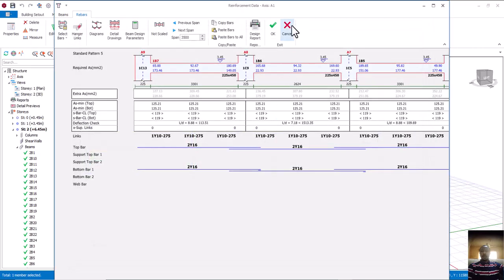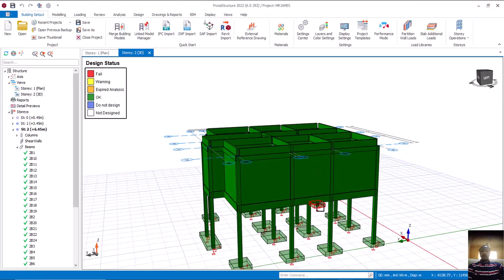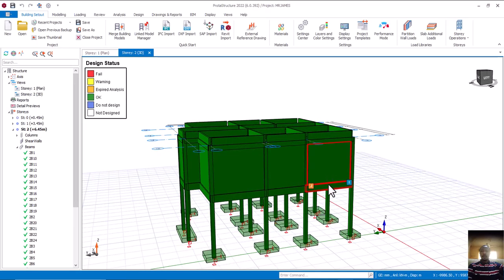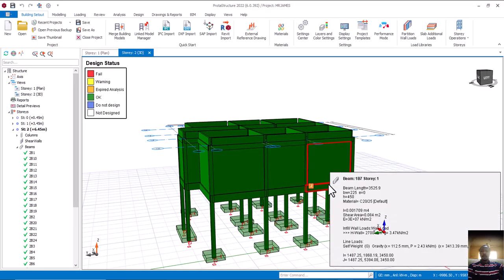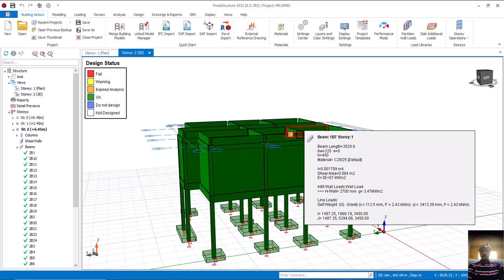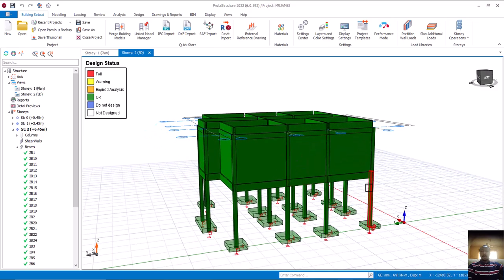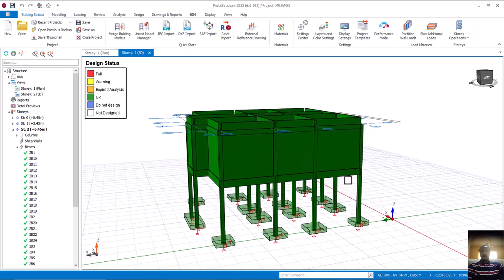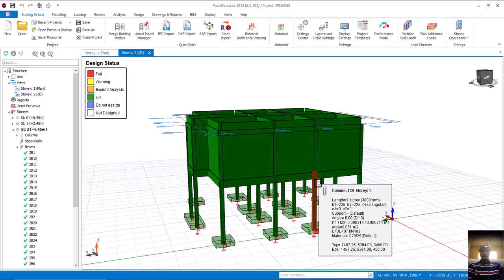So now that you have done these settings, the next thing, how do you take it to AutoCAD? To take it to AutoCAD, there's another setting that you need to do in what we call Prota Detail. You have to arrange it from Prota settings. Now we have done the settings here. Let's now see how we can arrange it from Prota Detail before we export to AutoCAD.